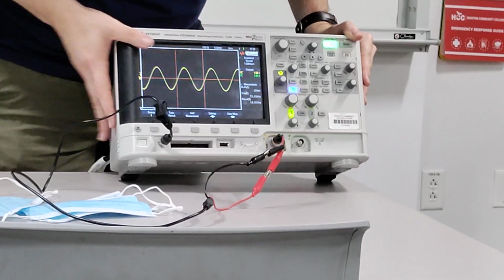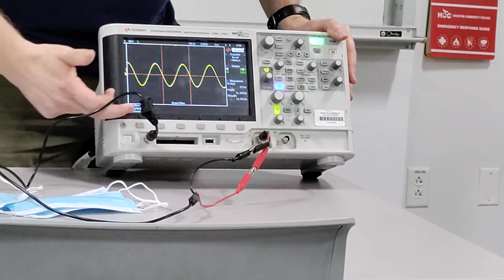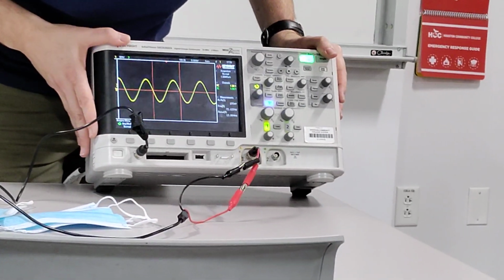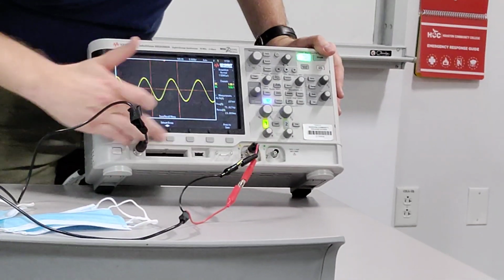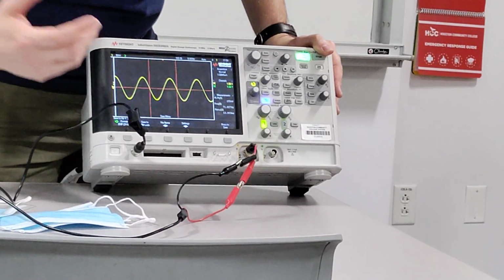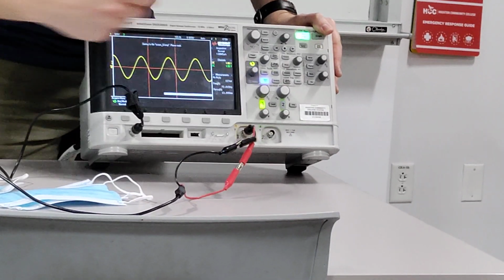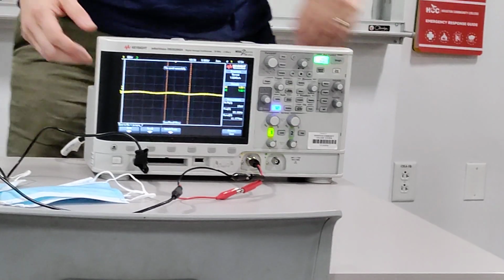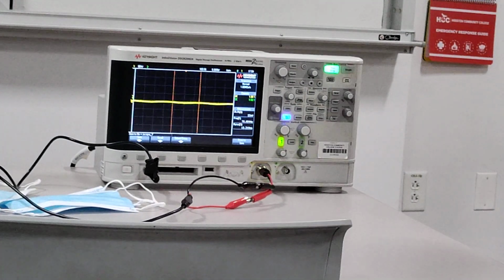And the way you do that is you click a button called Acquire, which is there, and it's going to come up with options at the bottom. Acquire mode is normal, and I want to save this. So I can click Save, and it's telling me what format I want. I'm doing a bitmap. I'm saving to this USB, and then you hit this button to save. And we're done. And now there's an image of this on your USB stick. And those are the things that can be used in your lab report.